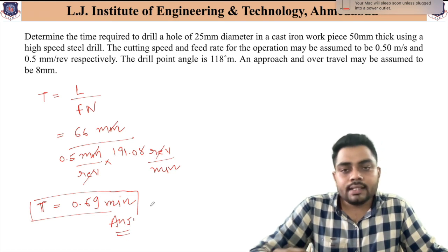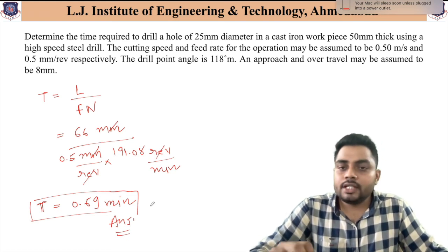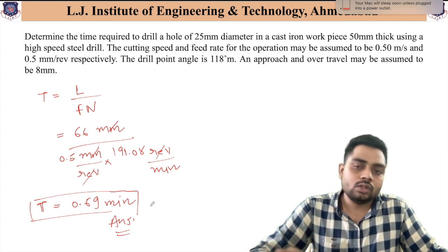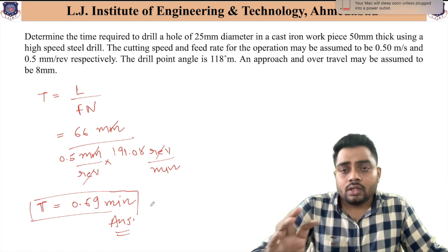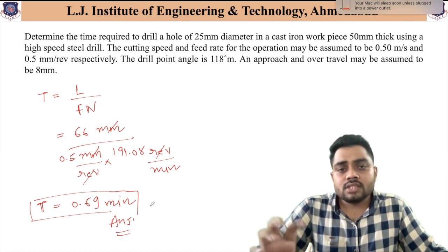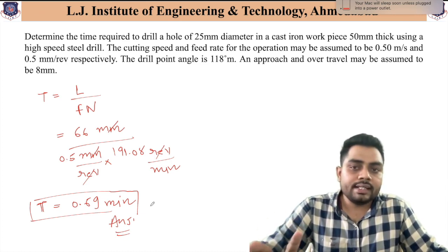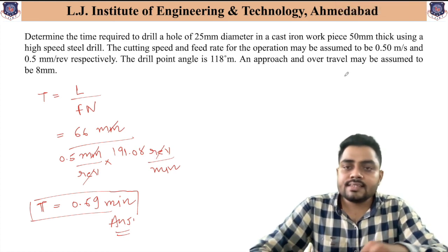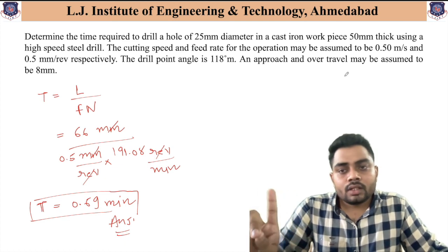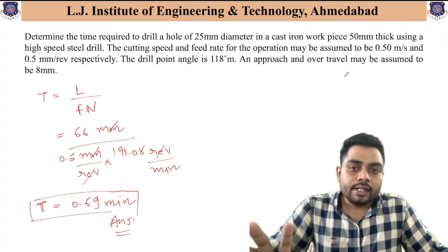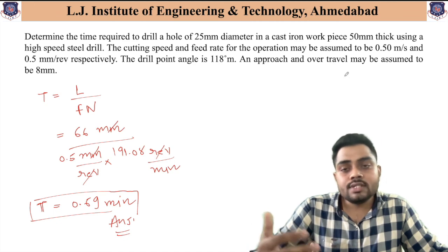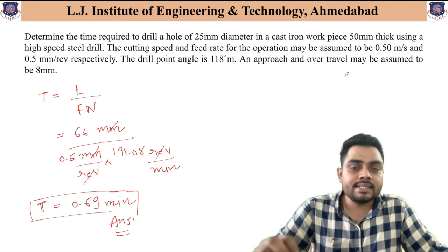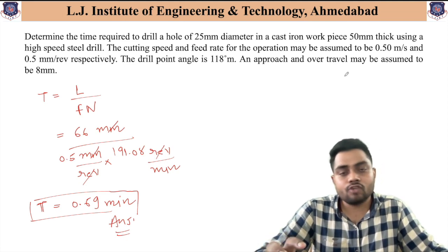So I hope you get the clarity how to solve this particular equation and how to find the time required to drill a hole. So in this particular lecture we have studied the two main important criteria. The first one, that is the time required to drill a hole using the equation L divided by Fn, and we have also understood the basic details regarding the work holding devices for the drilling tool.